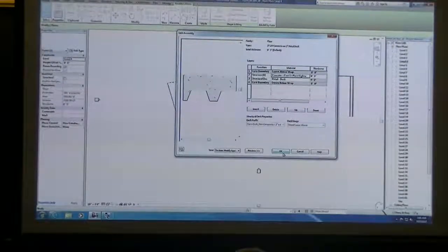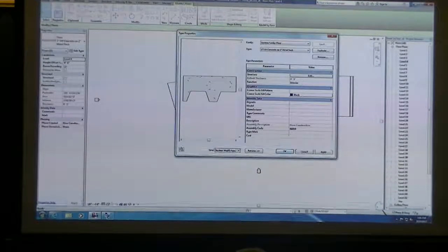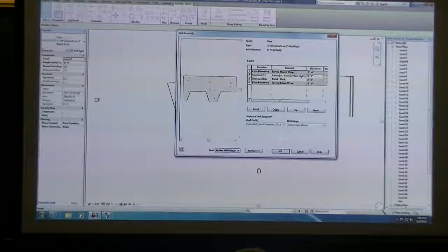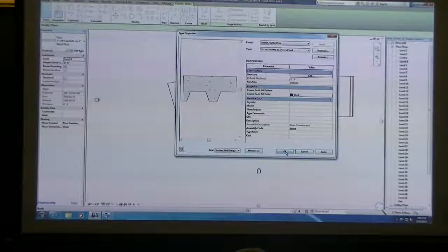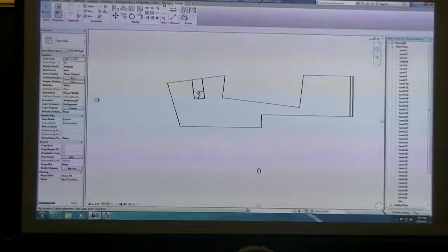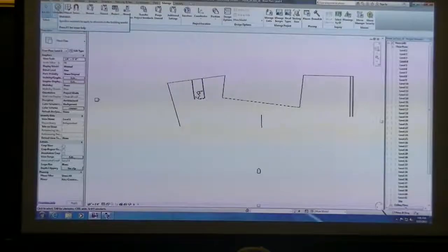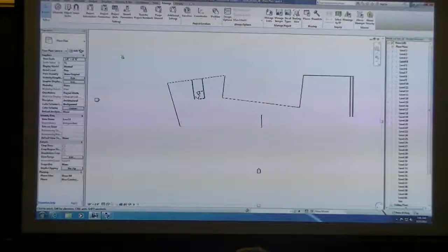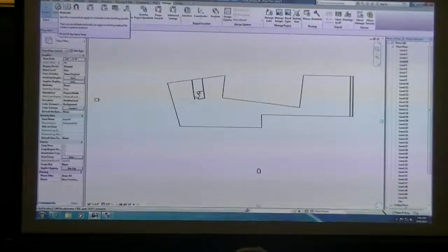Is it under type properties? I don't see this one. Yeah, so once you've clicked on your floor, under structure, click on edit, and then you're under your materials, you just click in there and go ahead and change that material. You can also get to that in the same way under your manage tab. If you don't want to have to click through all those different icons, if you knew ahead of time that particular material happened to be lightweight concrete, you could just click under your materials and then do the editing there, just like we did with the renderings.